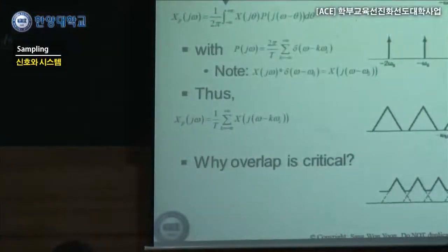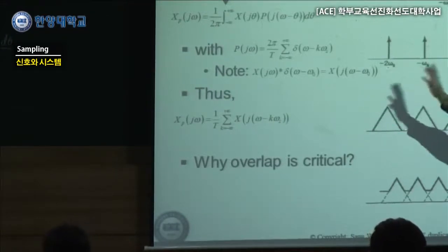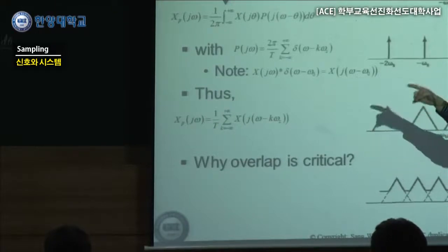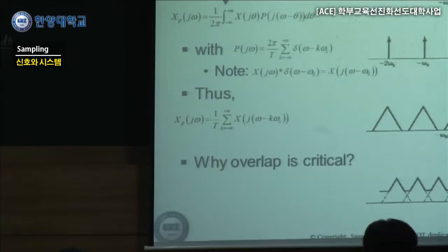So first of all, over there, x is our original signal before multiplication, which is continuous time. After multiplication, they change to a discrete time signal, right? So x before multiplication is a continuous time signal. After multiplication, they are sampled, so they are a discrete time signal, which is called x_p. So x over here is a continuous time signal, so their Fourier transform is the continuous time Fourier transform, which is not periodic.